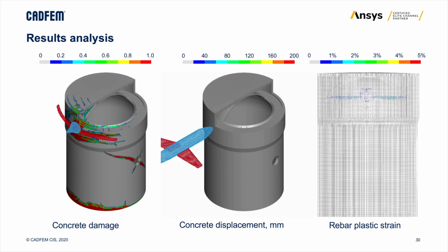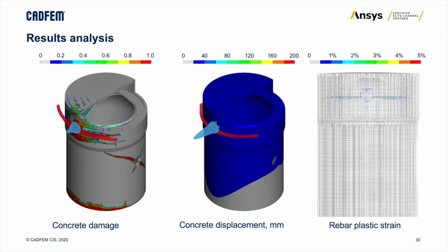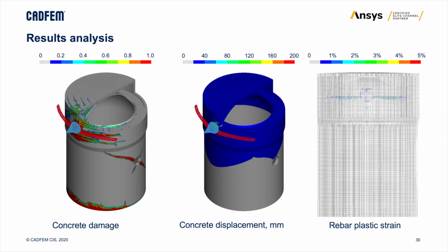For simplicity of this presentation, I show you only the sum of all displacement components, but of course it's better to analyze them separately. You can see that our construction oscillates near a new position of equilibrium, and the maximum deflection is under the fuselage impact zone. But after the end of the simulation, the general construction displacement is only about 4 centimeters.